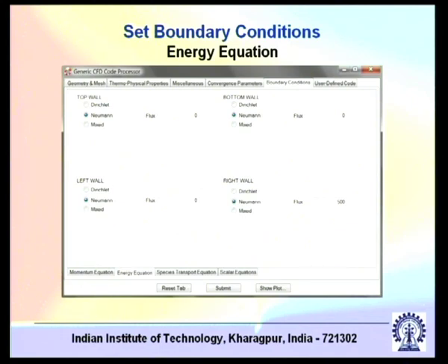Why? Here the problem is a time dependent problem, an unsteady problem. An unsteady problem can evolve from an initial condition. At time equal to 0 you have a particular value of temperature and that is a unique value, it is not an artificial iteration driven value. If it is an iterative solution, then even if it is a steady state problem you could start with an initial guess, but that is a guess, an artificial initialization.